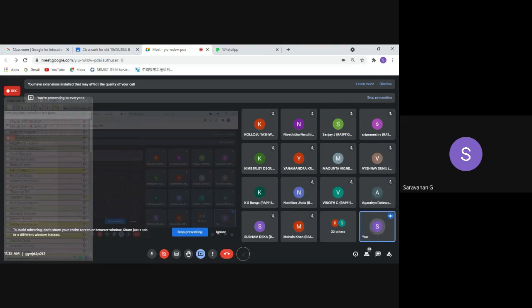Using that, in terms of gamma, R, and T, and using density in terms of pressure, and then substituting all these things together, you will get these three expressions. Nozzle expansion ratio A by A star. Another one is mass flow rate through the nozzle, or through a duct, as you can call it in some cases. The third one is the thrust coefficient for our case, the rocket system.